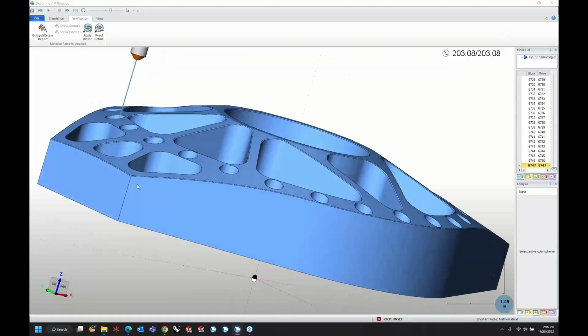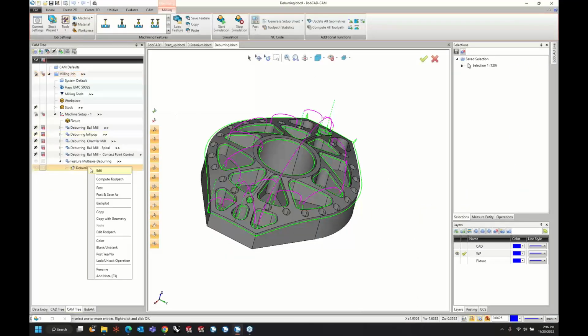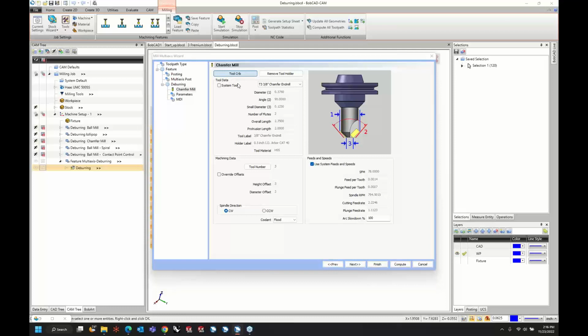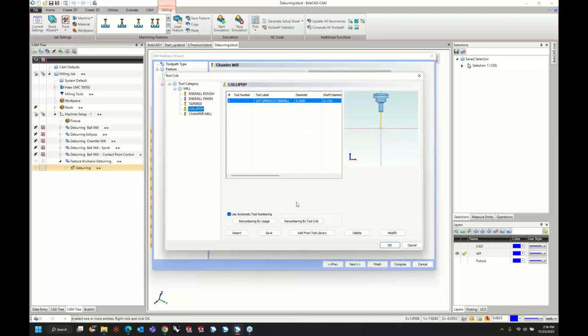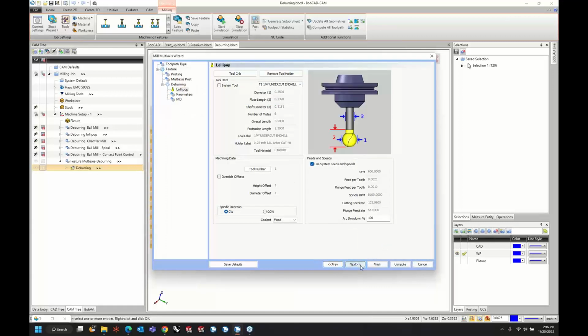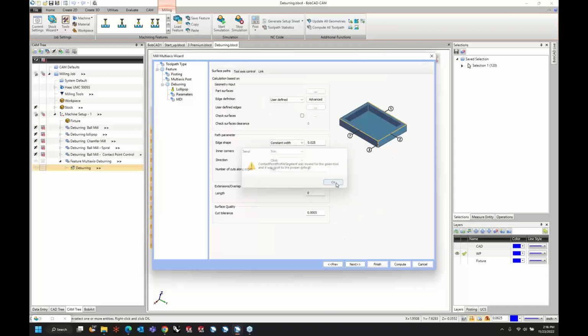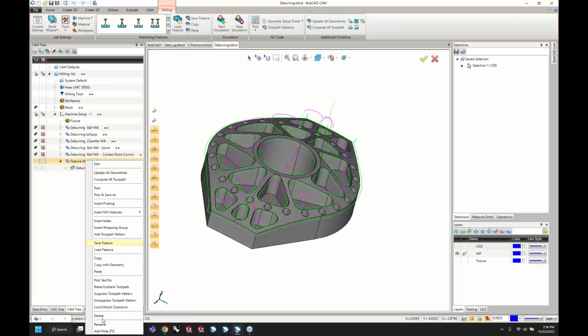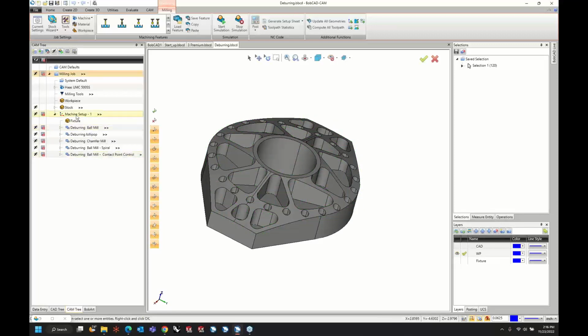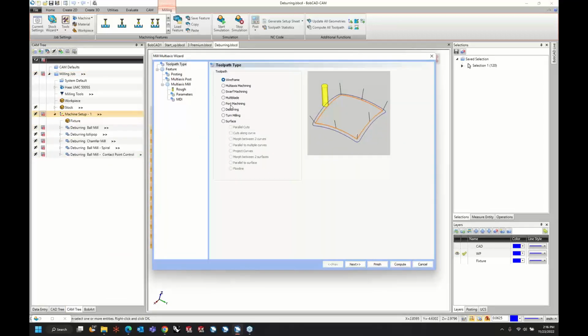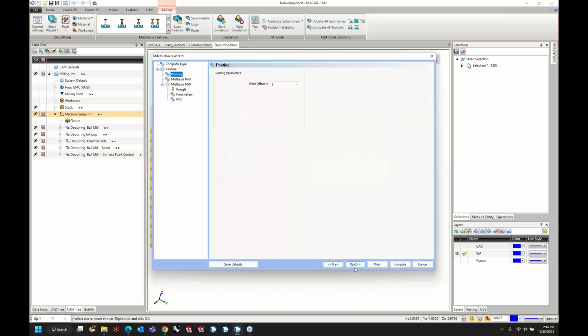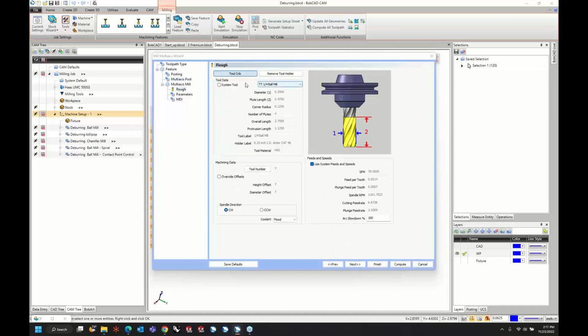Now, if I was using a lollipop cutter, I can actually go down this wall there. Let's minimize our simulation there. So let's change this to a lollipop cutter. Looks like they already have one in here that'll work since we already have these toolpaths on it. Oh, actually, I want to make this as a new feature. So let's delete that. Let's make a new one. Deburr. And I want to use a lollipop cutter.